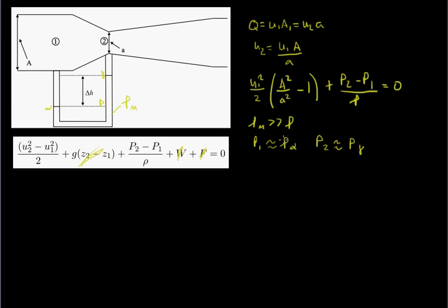That looks like a rho, but it should be a P, so P alpha. Okay, and then from this hydrostatic equilibrium, we can see that our P alpha is going to equal P beta. So I'll say that P1 is equal to P beta, and then P beta will equal P gamma, which is approximately equal to P2, so it's going to equal P2 plus rho m g delta H.